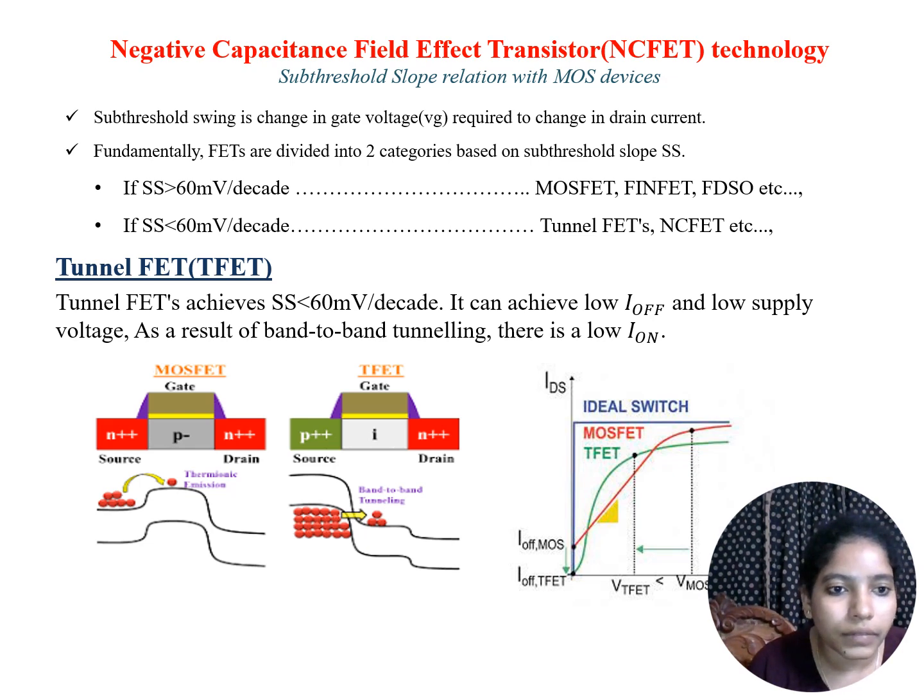Here is a MOSFET structure and here is a TFET band structure. So here the electrons move from source to drain. When the electrons acquire high potential, they move from the valence band to the conduction band. In tunnel FET, due to this intrinsic region, the electrons will penetrate the barrier of the valence band and go to the conduction band. It results in band to band tunneling because the electrons have penetrated the barrier and enter into the drain.